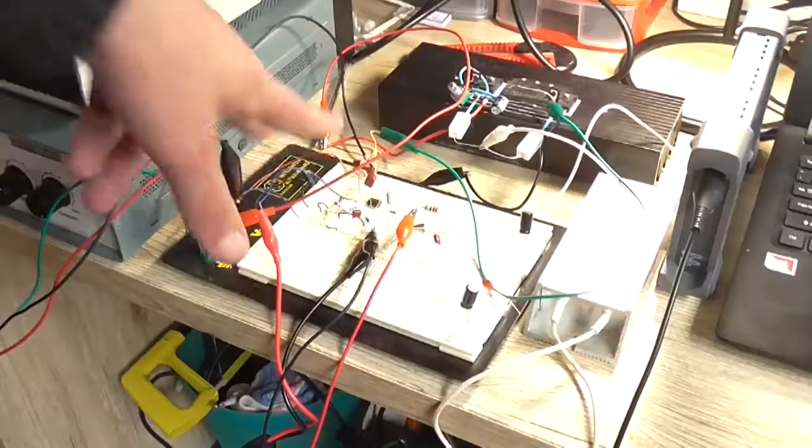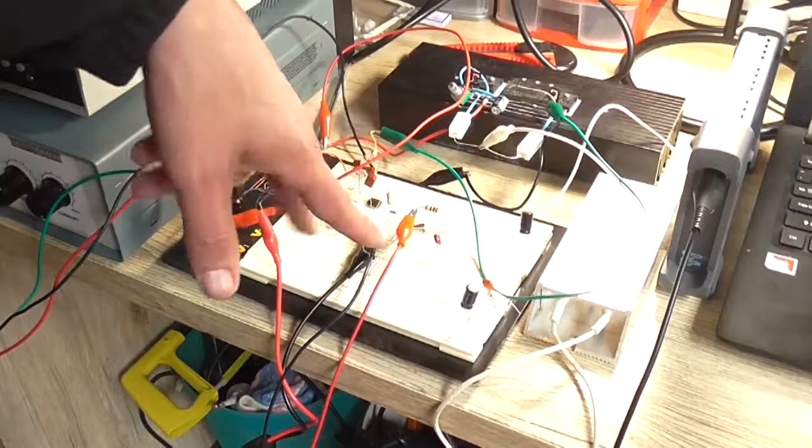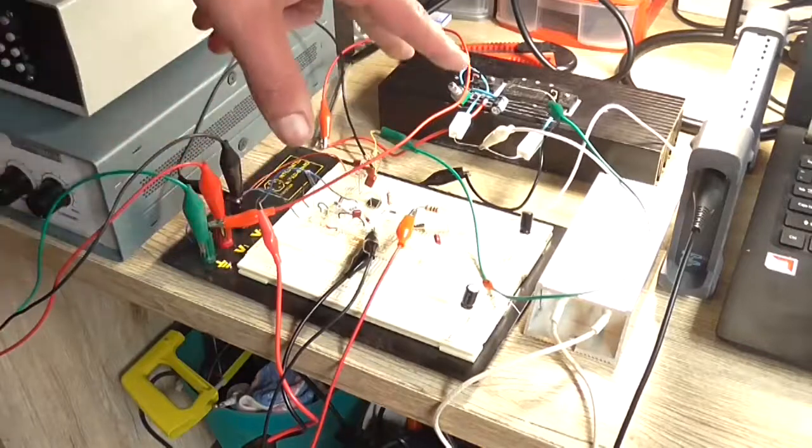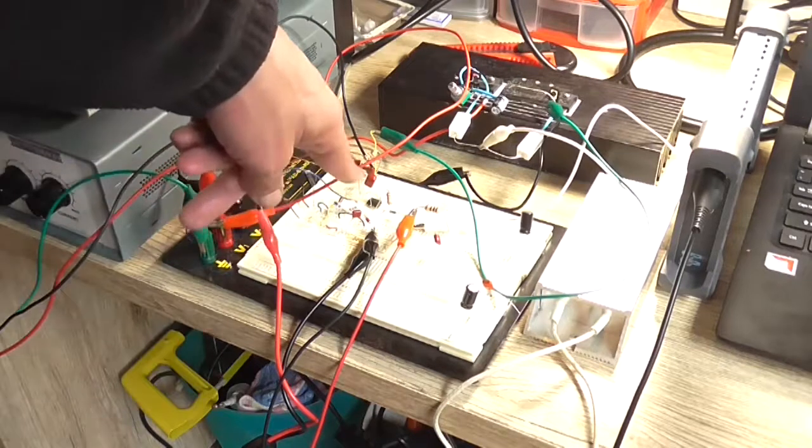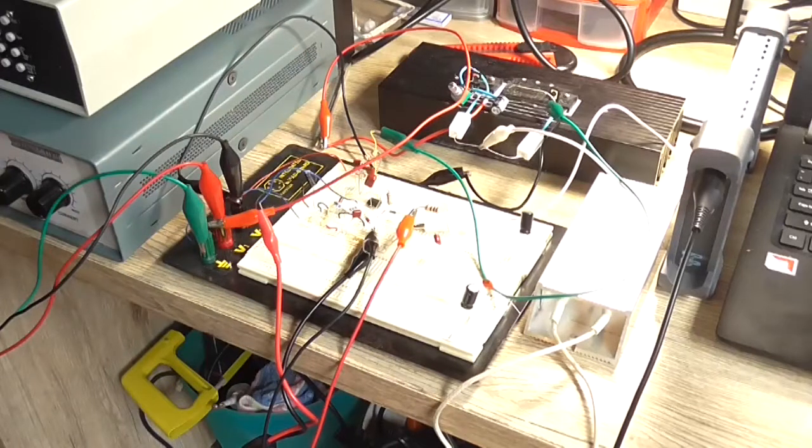Now that could be the Zener diode network is not actually producing plus minus 15 volt equally. So I could try upping the voltage, and upping the voltage just makes it look more square wave. So I'll leave it at 21.2 roughly. I'm going to see what the voltage is across the pins that it's supposed to be. In fact, I'll turn it off and make sure that I've actually wired it correctly.